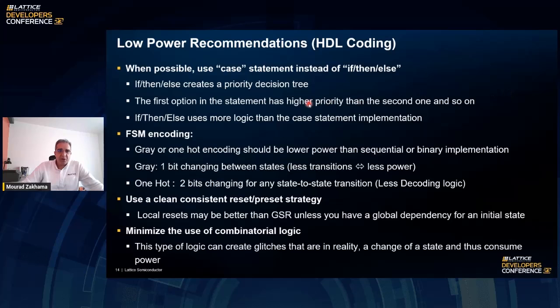The first statement will have a higher priority than the second one, and so on. If you do a case statement, they are all evaluated at the same time and have the same priority, and there is no extra logic used. So the case statement is better for hardware implementation unless you need priority between the different cases in your design.